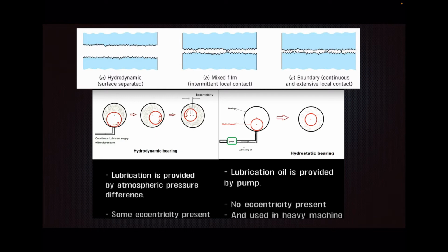Hydrodynamic lubrication is provided by the pressure difference, and some eccentricity is present. Hydrostatic lubrication is provided by the pump, and there's no eccentricity.